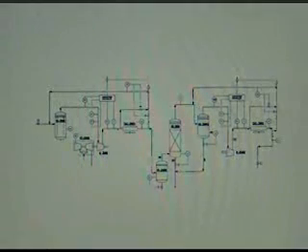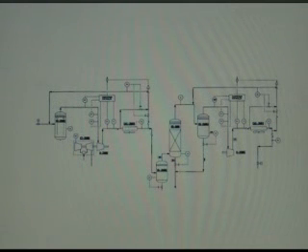This is the process loop for the compressors of that gas turbine compressor train. You can see the gas turbine here, directly coupled to the low pressure and then the high pressure compressor. At the point in time this valve was closed and that isolation valve was closed, the entire loop had been depressurized down to the flare, but there had been no blind swung because all of the operation was taking place in the gas turbine, which is physically isolated from the compression loop.